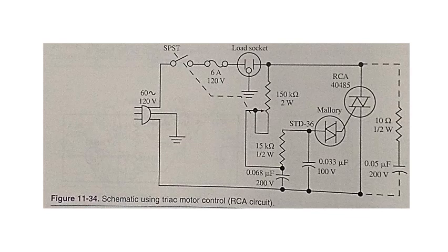However, since two north poles repel each other, as do two south poles, motor action continues in the DC motor when AC is applied. For best results, a series motor should be used. When the shunt motor is connected to AC, the inductance of the field windings causes a phase displacement. This impairs motor action.